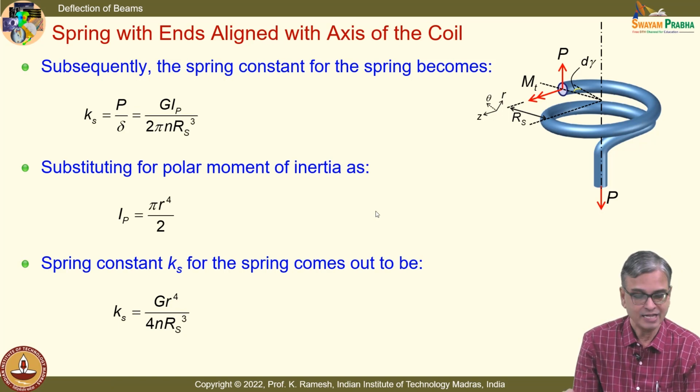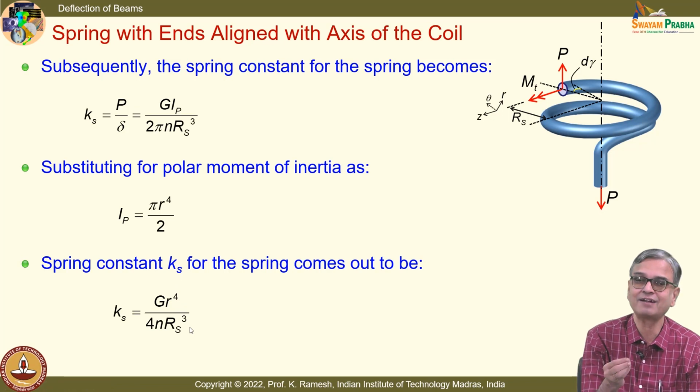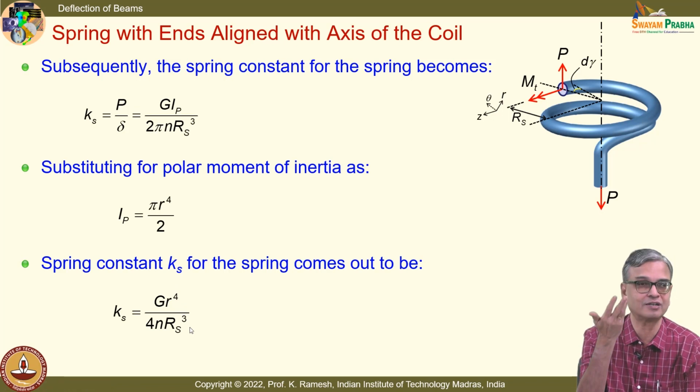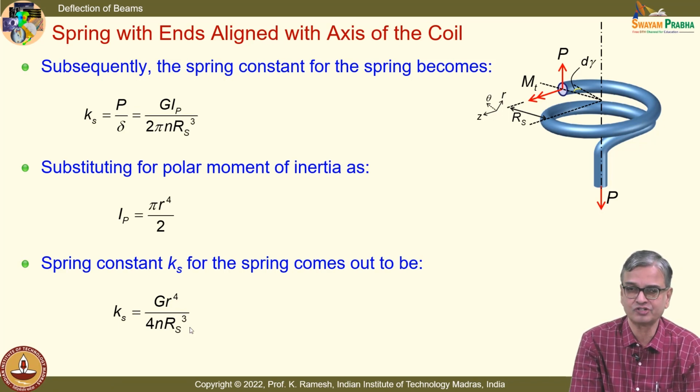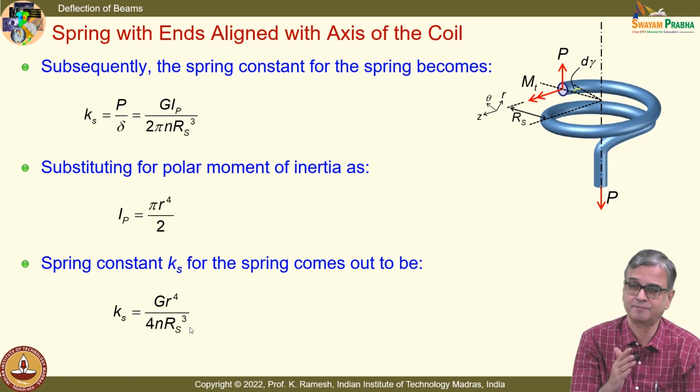And in contrast to your shaft design, springs are always made of alloy steels, whereas shafts are made of mild steel, because you are looking at the stiffness. You are not designing based on strength. So it is sufficient that you use a mild steel for routine purposes. High end application, they may change the material.